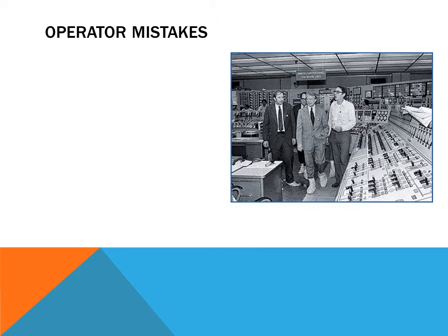Unfortunately, when that stuck open relief valve occurred, the operators didn't recognize it. They didn't recognize it because the downstream temperature monitor, which is installed to give you an alarm that it had relifted, had been in for a long time. It had spurious alarms on it, or frequently had issues with it. So the operators knew the relief valve did lift. They assumed the valve had reseated and the casualty was under control. They did not think this valve was stuck open.